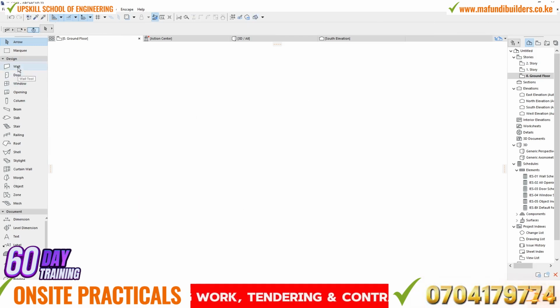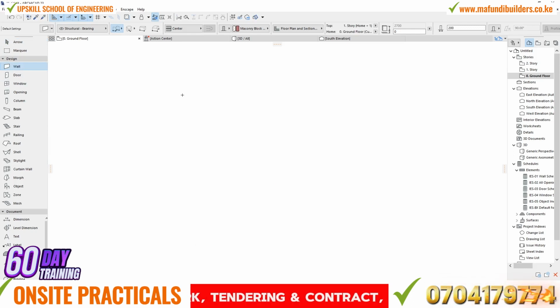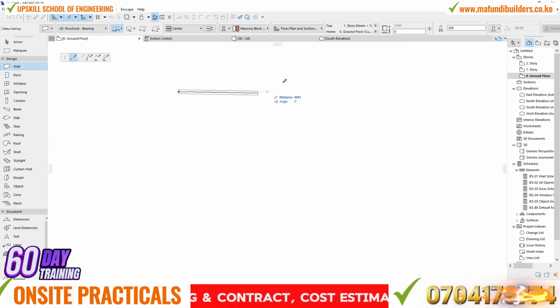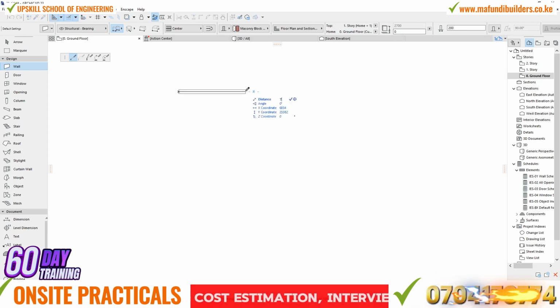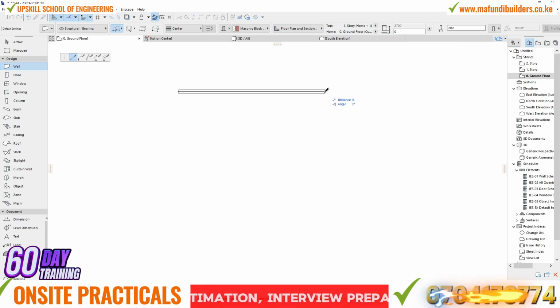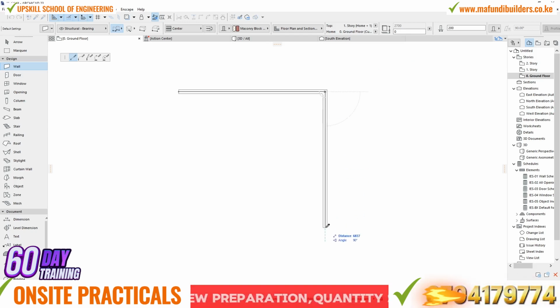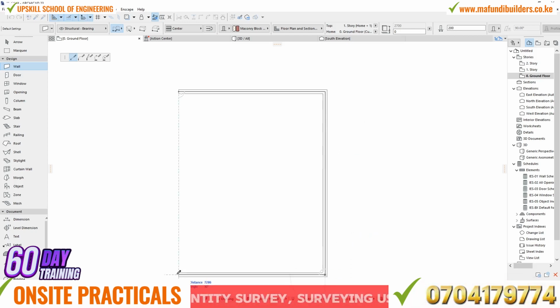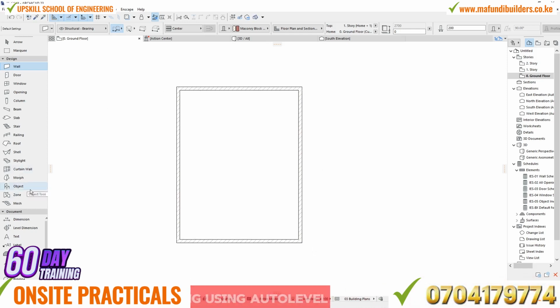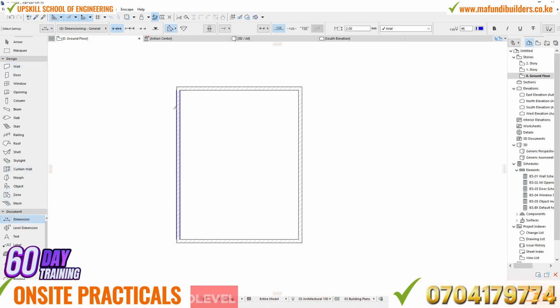So if I want, for example, to draw a wall which is, let's say, 7,000 inner to inner, what am I supposed to use? If my wall thickness is 200, I'm supposed to use 7,200. You see? So enter, and then on this side I want to use probably 9,000, so I'm going to say 9,200. You see? So I'm including the center to center distance of that wall.